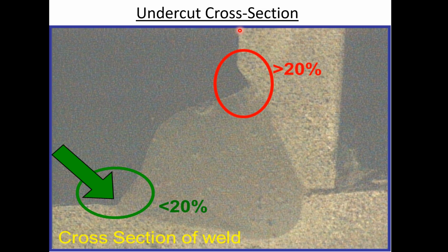Now, that extra heat input could cause issues back here, but you have to meet that criteria. Not too many specs address the beginning and the end of a weld, but there need to be some considerations there. At the beginning and the end of the weld, I'm going to call this a special Bob rule, and I'll tell you why I have it. I don't want any undercut in the first or last 25 millimeters of a weld.